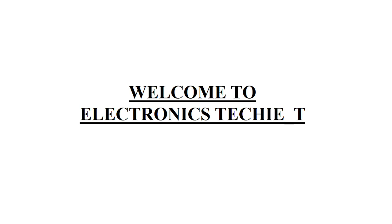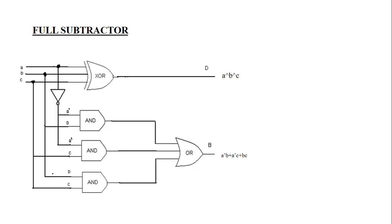In this video, we discuss the full subtractor. The full subtractor logic diagram looks like this. We already discussed the full adder. The difference is that the inverted output of A will be given to the two AND gates here. In the previous video, we discussed the full adder.